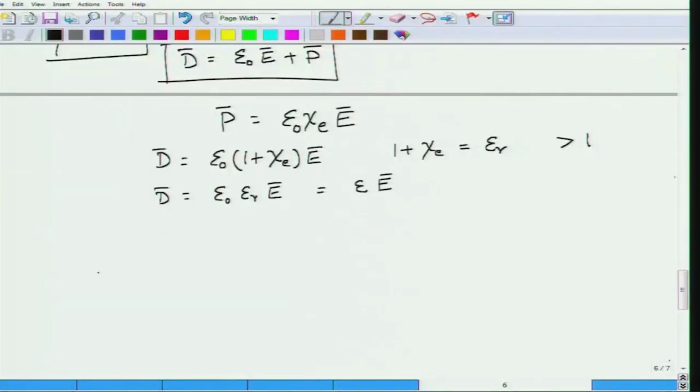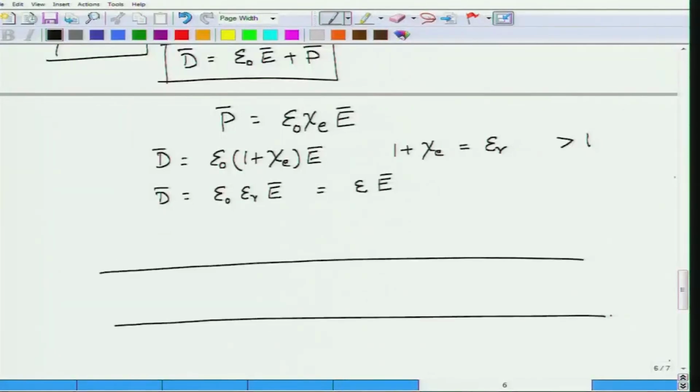In this course we will not be looking at nonlinear materials, we will be looking at linear anisotropic materials. Anisotropy of course makes its entrance quite late in the course. Okay. Alright, so we have D is equal to epsilon times E. Now let us ask the following question. Suppose I have a dielectric slab, okay, let us consider this to be a Teflon slab, and this Teflon is given by a susceptibility chi e of 1.1, okay, at some temperature this chi e is 1.1. What can we say about the fields inside and outside?